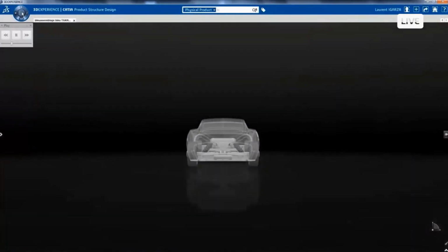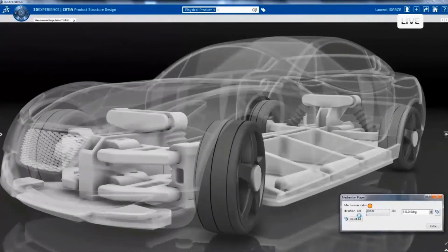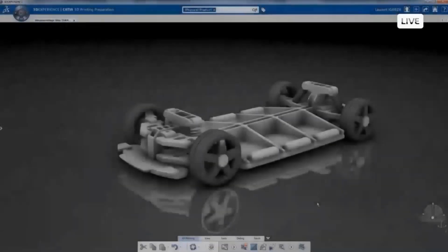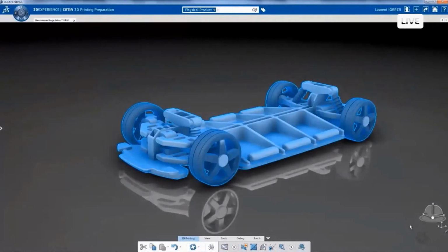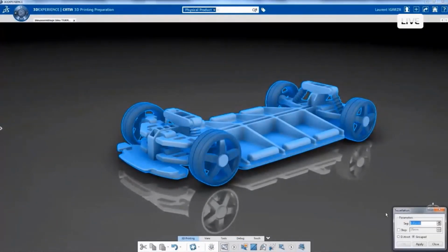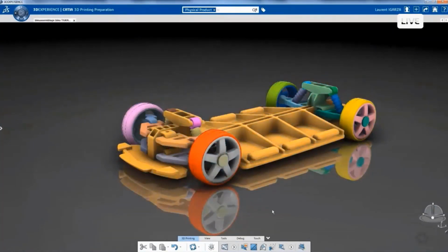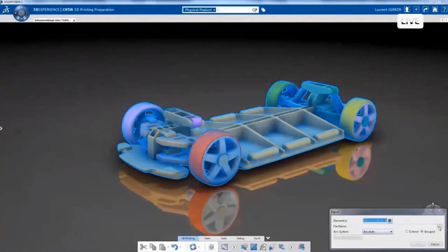And what we want to do is to take all these solids from the assembly, that's in the CATIA assembly, as you see here. And from this complex assembly, generate an STL file in one click, like here. So create an STL file by taking some constraints like chordal deviation and maximal size of the facets. And of course, after that, you can export your results on disk.